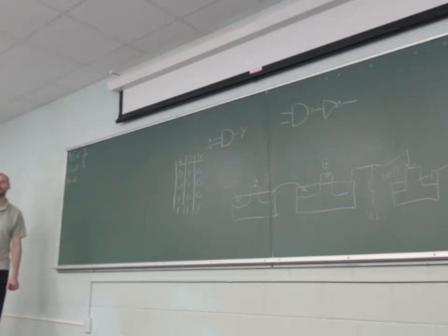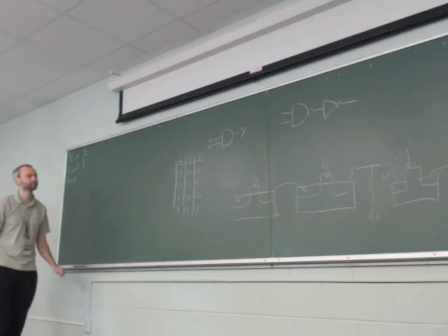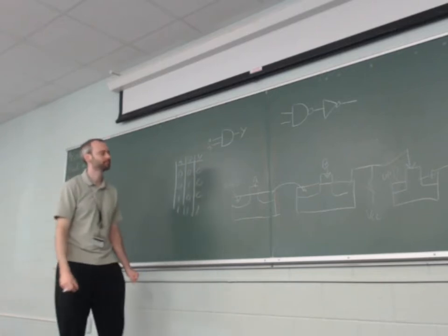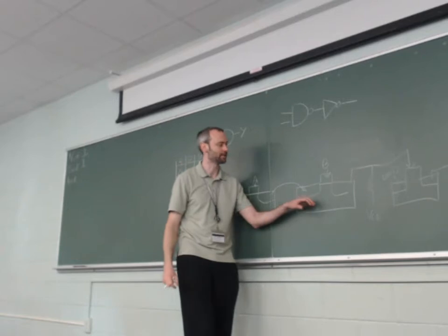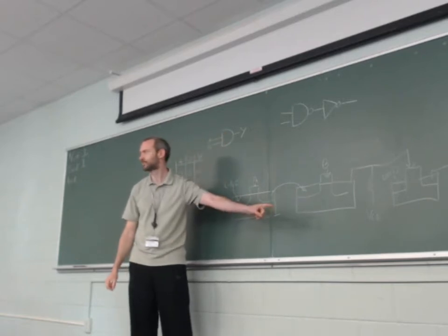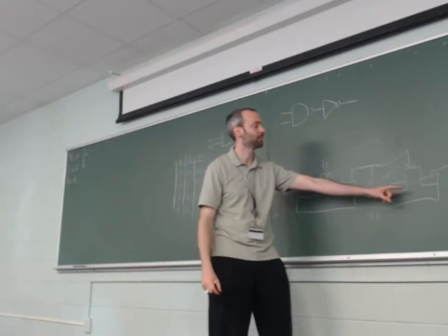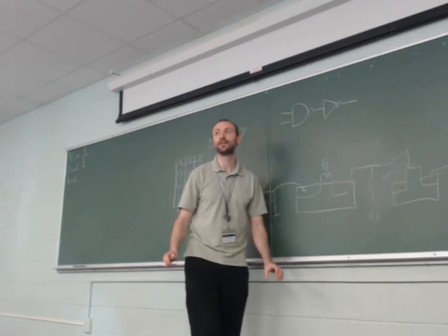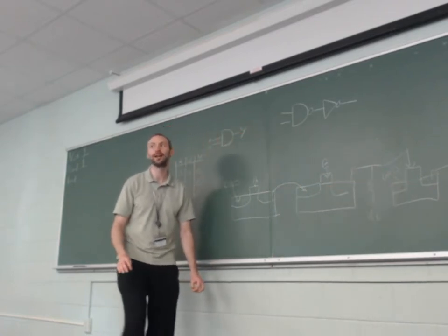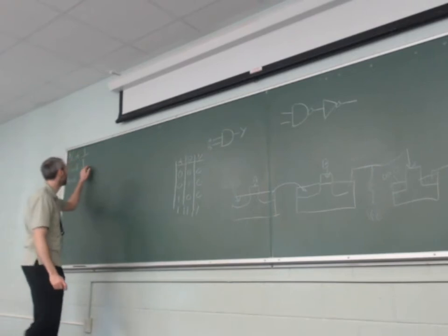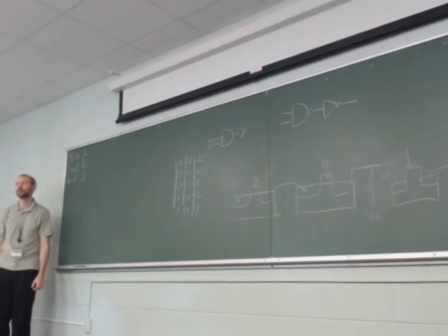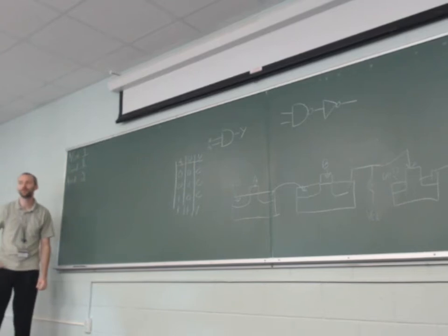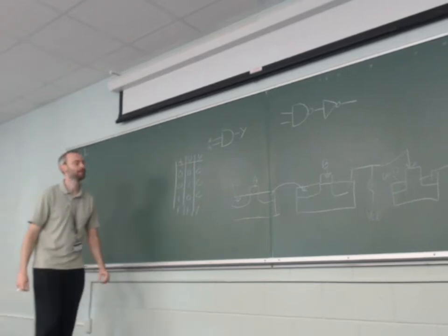What's the gate delay here? This one. Why is it 2? Because first you have the NAND going in parallel. So then the NOT happens after. So you add the NAND and the NOT. All right, is it very clear why the NAND is 1, but the AND is 2? No.